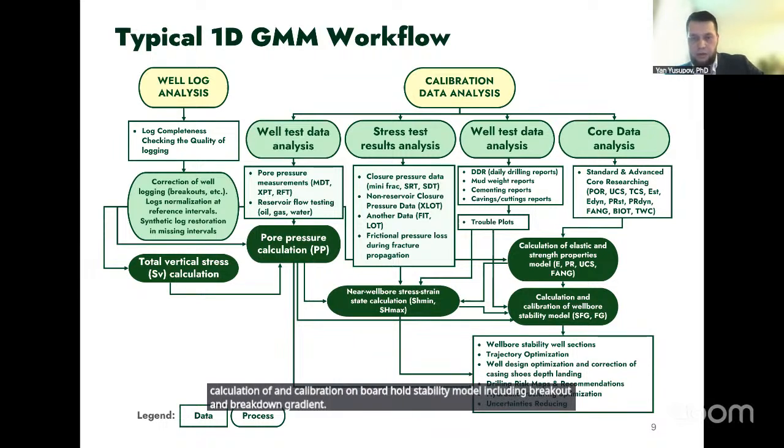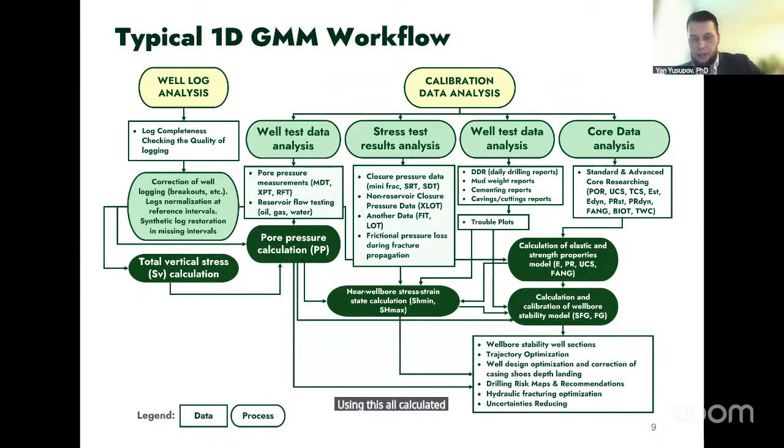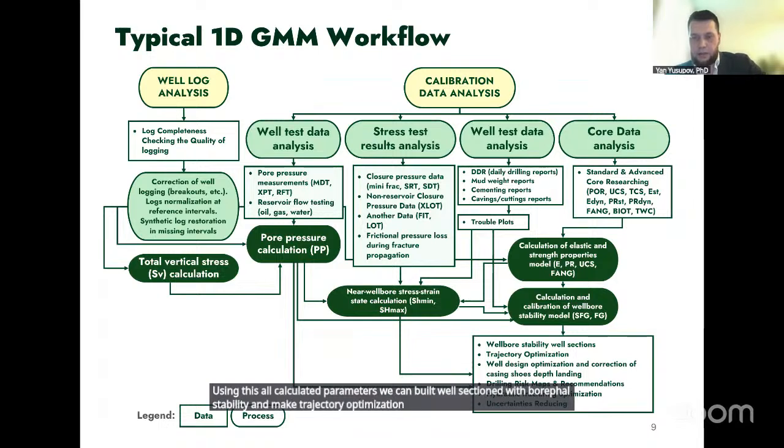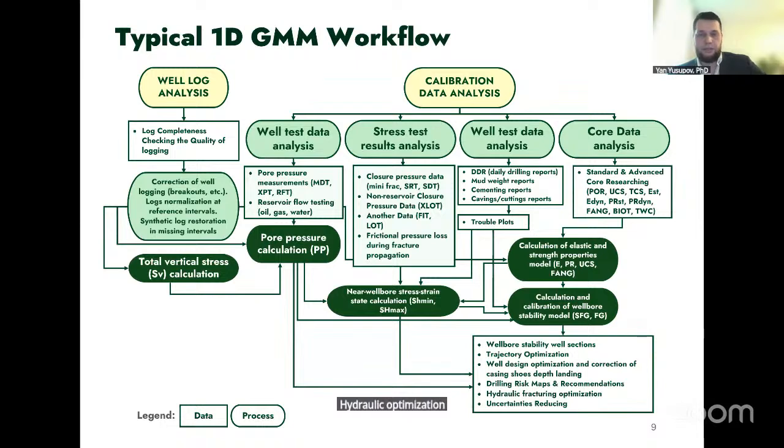Using all these calculated parameters, we can build a well section with borehole stability, make trajectory optimization, make also a well design optimization, correct the casing shoe depth landing, build a drilling risk map, and develop recommendations for improvement of the drilling process, hydraulic optimization, and uncertainties assessment.